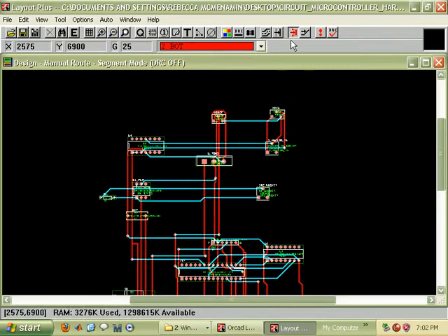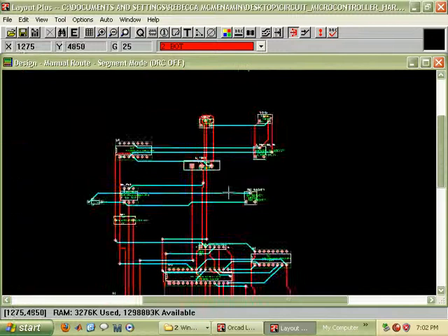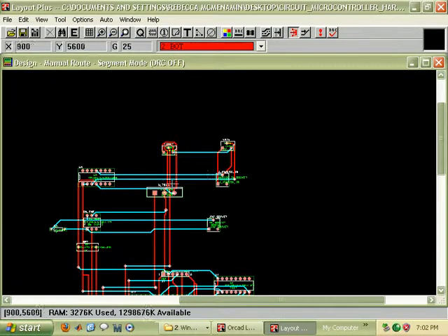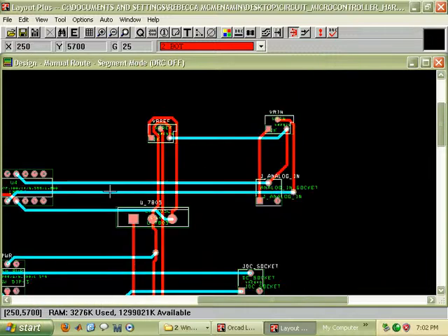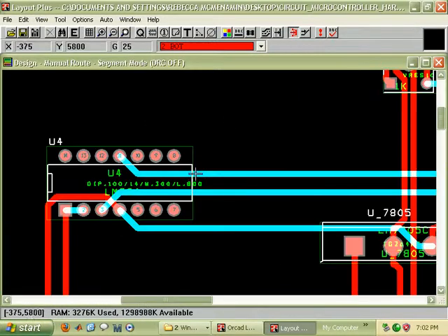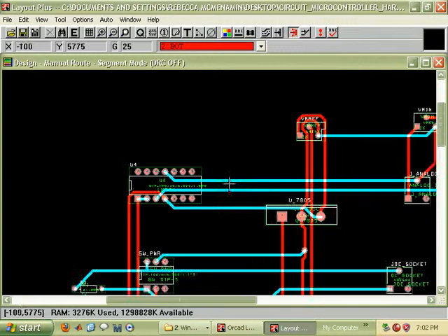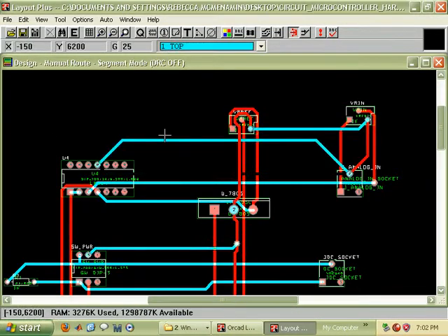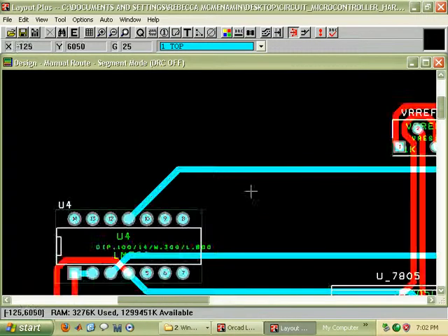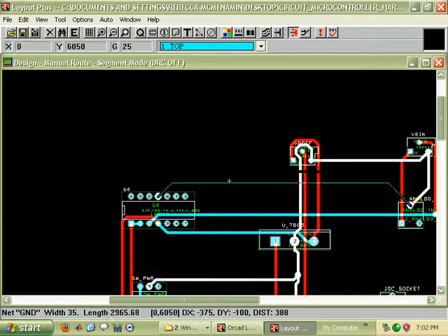And suppose you need to change any layout connection after the auto route, most of the cases we need it, because the way the software does it, most of the time we don't like it and we may need to change it. So how to do the change? You select this one, press, and then click the layout that you want to change.